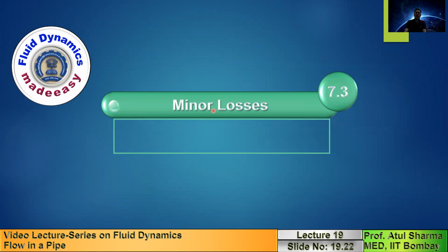Finally, after presenting the friction factor for the laminar flow and turbulent flow, I have presented two types of friction factor, Darcy's and Fanning, for the laminar flow. For the turbulent flow, I have only presented the Darcy's friction factor, which corresponds to the non-dimensional pressure gradient.